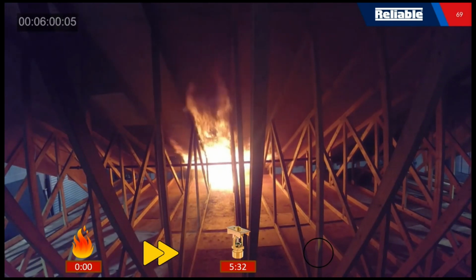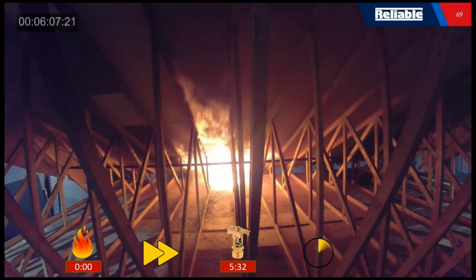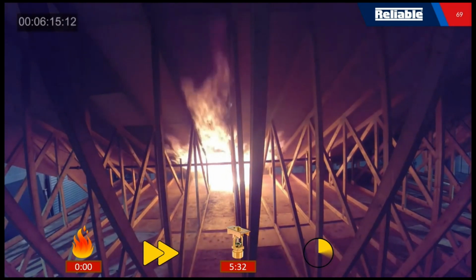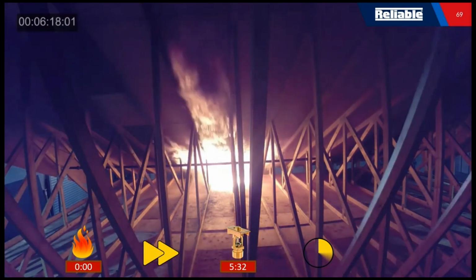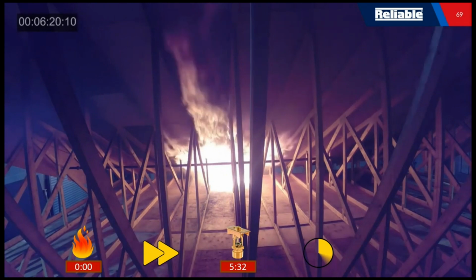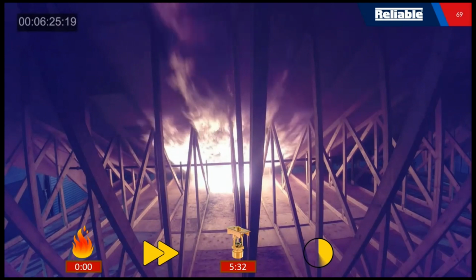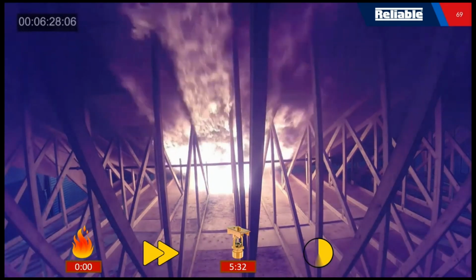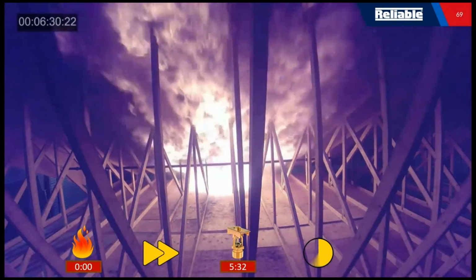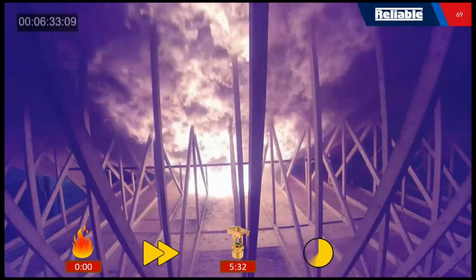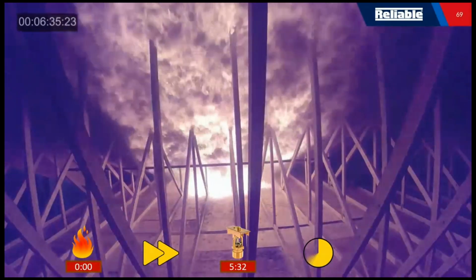And now we have our first sprinkler activation at 5 minutes and 32 seconds. You'll notice there's no water being discharged at this point because we are attempting to get a listing for a dry system. The laboratory is withholding the water for 60 seconds, indicated by the pie chart down there. Now, we are not fast forwarding this. Since that sprinkler is activated, you're watching everything in real time. If you've ever heard somebody tell you that fire grows exponentially, you can truly see that in this 60 seconds. We're only about 3/4 of the way in on this delay.